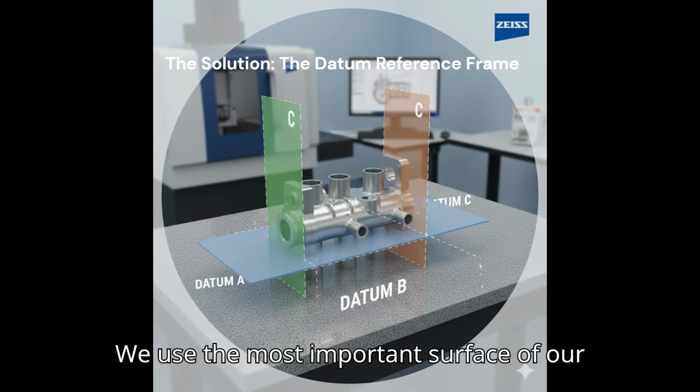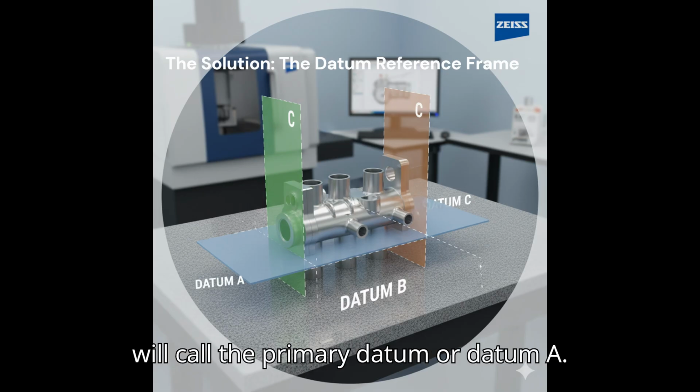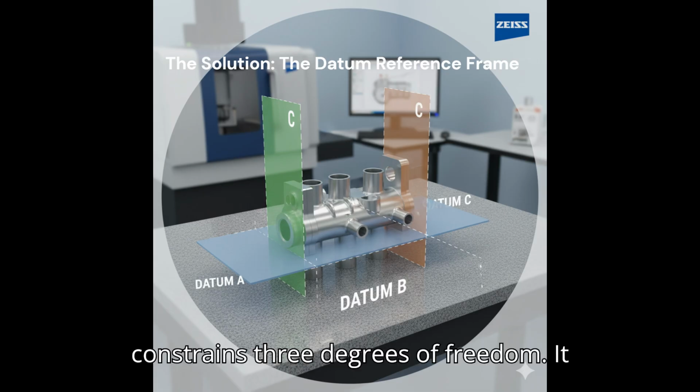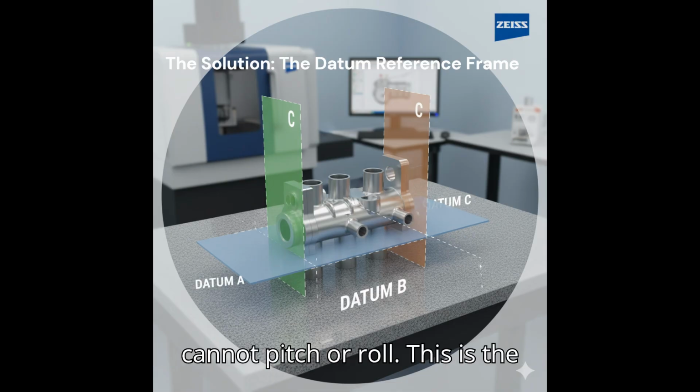We use the most important surface of our part to define the first plane, which we will call the primary datum, or datum A. This is usually the largest, flattest surface. Placing the part on this plane constrains 3 degrees of freedom. It can no longer move up or down, and it cannot pitch or roll. This is the foundation of the famous 3-2-1 principle.